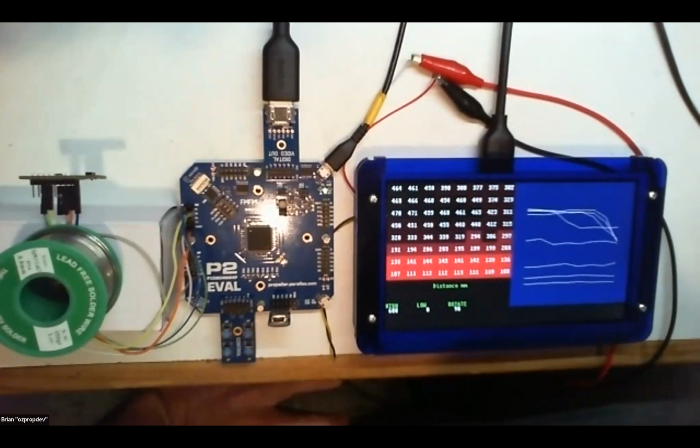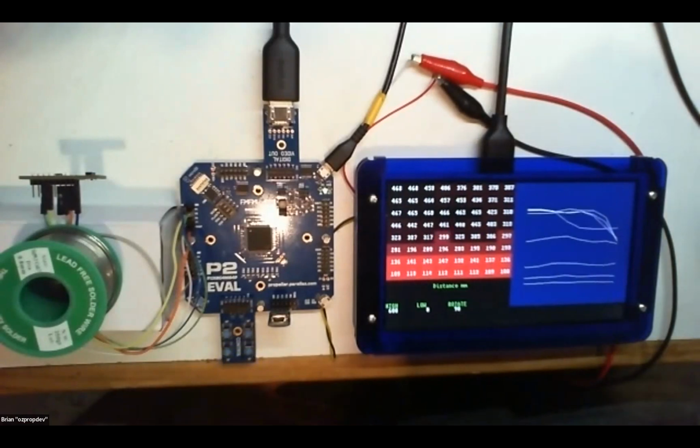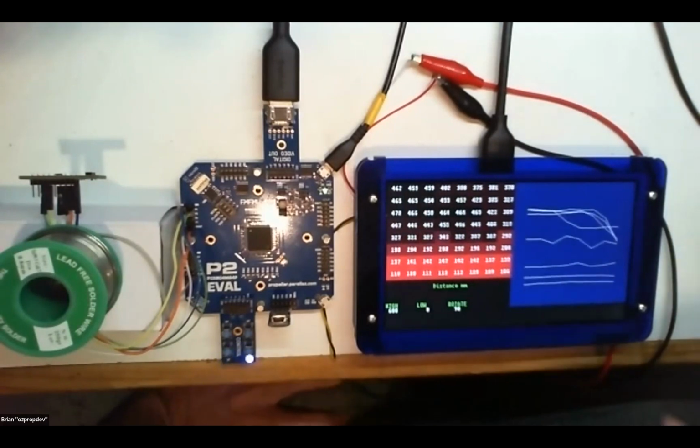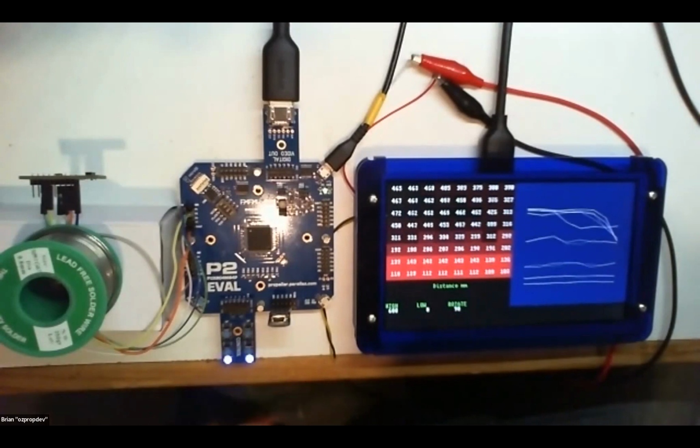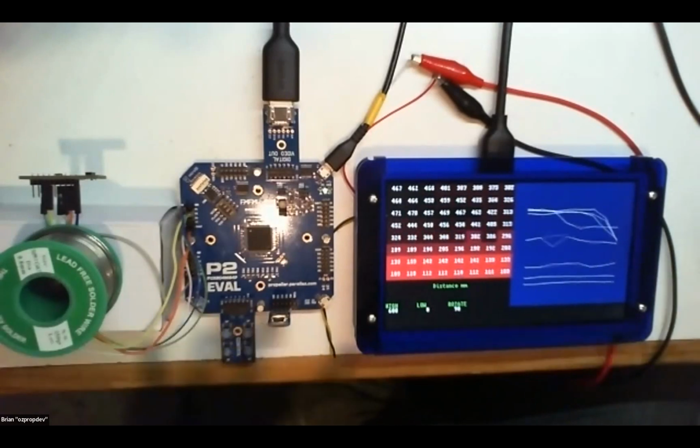It'll give you reflectance values, and sometimes you'll see a little spike where it's getting a misreading. There are status bytes that you can read that let you know that the ranging calculation was in error. I didn't have time to hook all that in to make it ignore the last reading, but basically you have a field of view of 45 degrees and you're getting 64 readings at once.